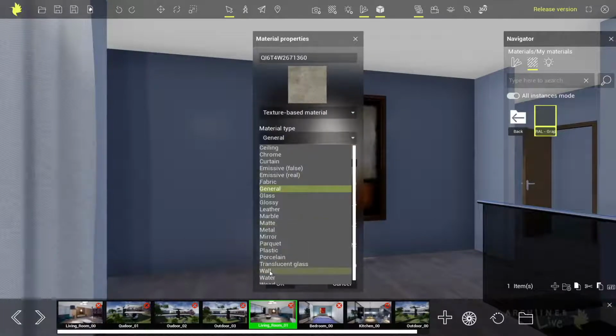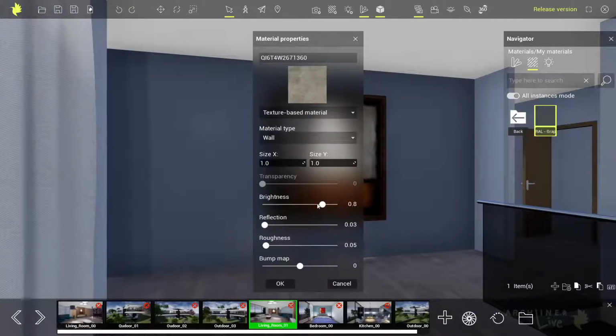And again, this is actually a wall surface, so I would just use the same. I won't change any of the defaults. Well, actually you can also change the size of this material if you want. You can just type a value here, or you can use the slider if you want. But once you're done, you should take care renaming it, because in case of using a texture, the software will auto-generate a name, and you can rename it the same way you could rename any of those objects, but now I prefer to give it a proper name.